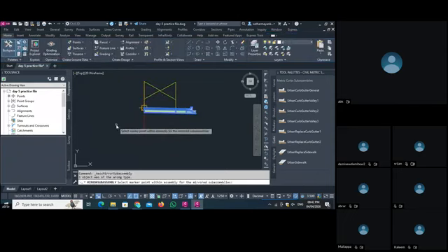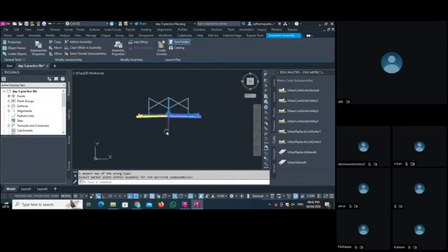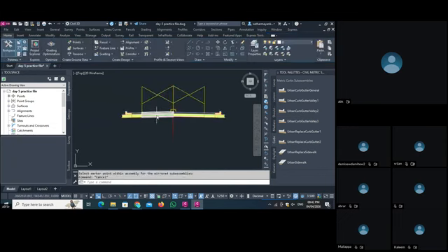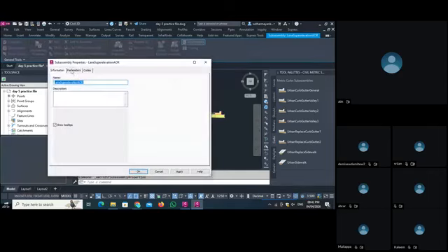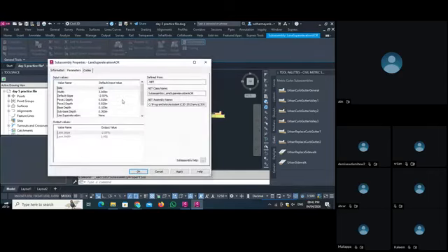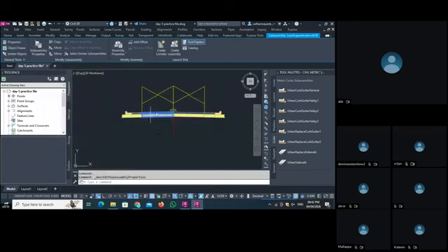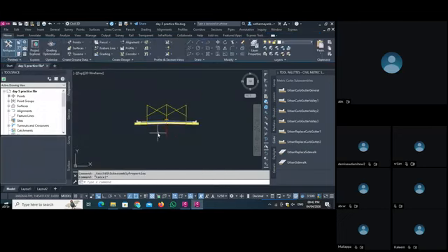A marker point is there, and they are asking us to select the assembly where you want to mirror. Select the baseline. So I select this baseline. As I select the baseline, all things are copied here on the left side. Now check: if I select the left side lane and go to the sub assembly properties, in the parameter you can see the side is left here. So now all set. Now I just create this basic assembly here.